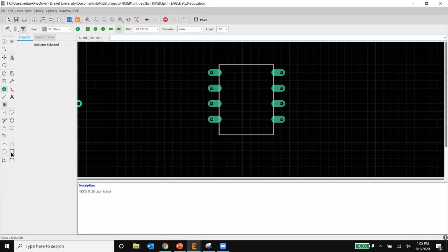Now when you design a component, basically to tell the person where these pins start and what their order is, you usually make an arc here at the top, just to let people know that it starts from this side.